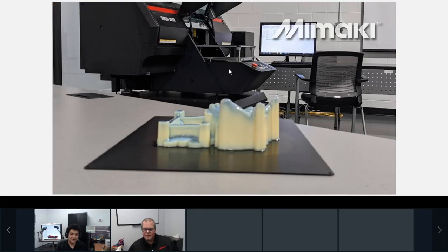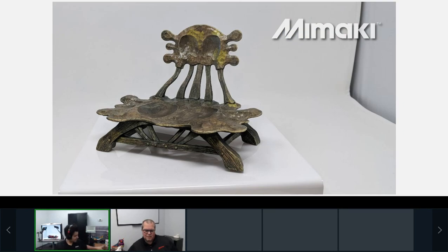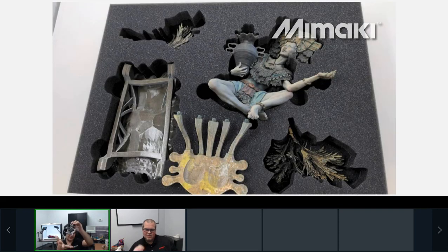Yes, please. So, for example, when it comes to optimizing and finding the purpose of the print, another advantage of doing assemblies is how to maximize your print size. In our newer model, the 3DUJ-2207, we have an 8 by 8 by 3 inches print envelope. But that does not mean I can't come out with a bigger print. That's the montage for this figure. It was divided into 3 different parts: 2 parts for the seat and another part for the body. If you put it all together, it's a much bigger print, and that's a way to maximize the print size.